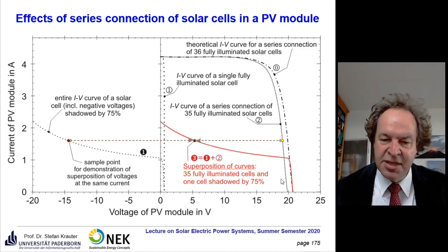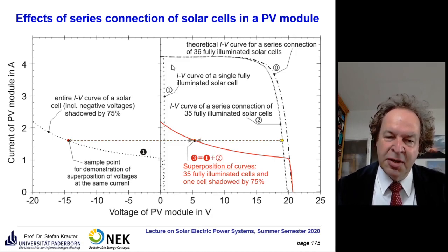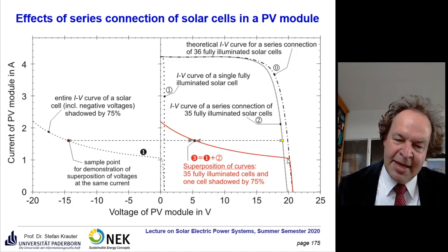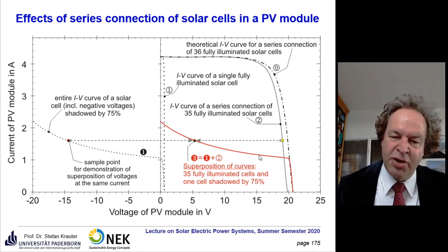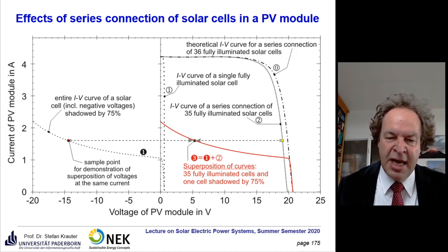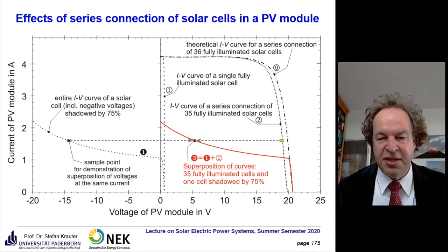And this you see here. The red line is our new IV curve, and you see it's much smaller than the other ones, and you have a very undefined maximum power point. Maybe it's here, maybe it's here, and in total you have drastically reduced power output, only due to this single cell which received a lower irradiance level. The overall performance is reduced, and it's not only one module, if you put many modules in series, maybe a whole PV generator is affected by that.